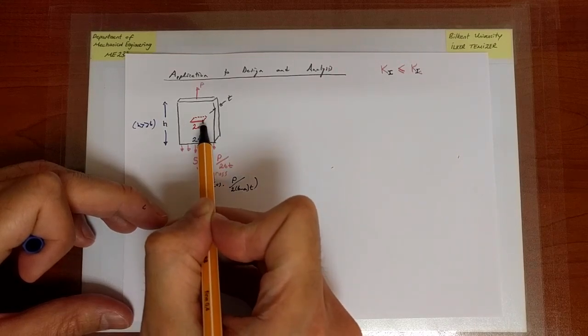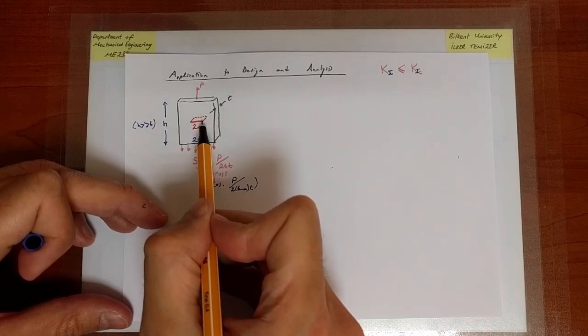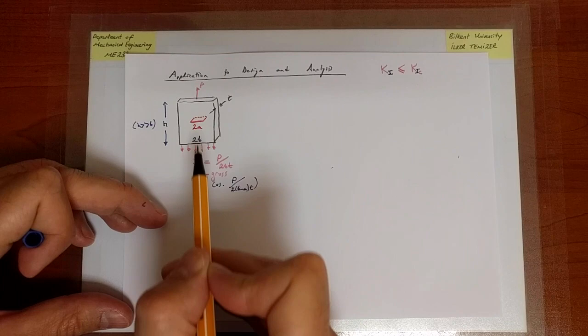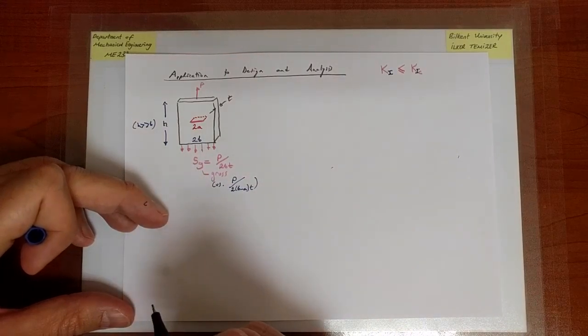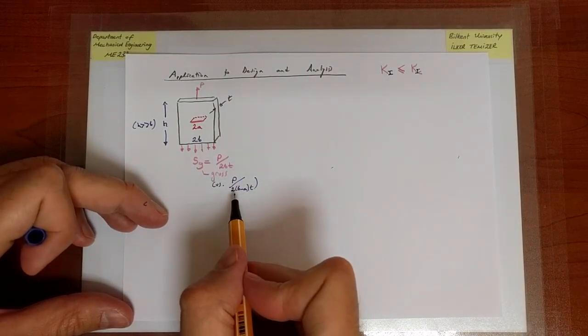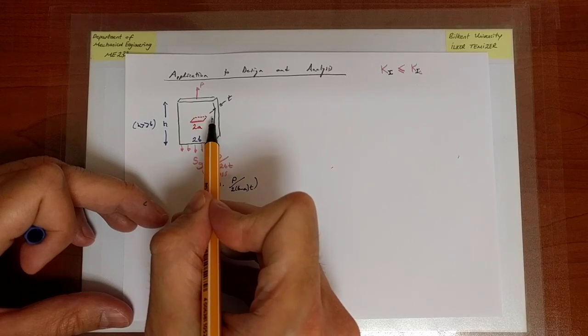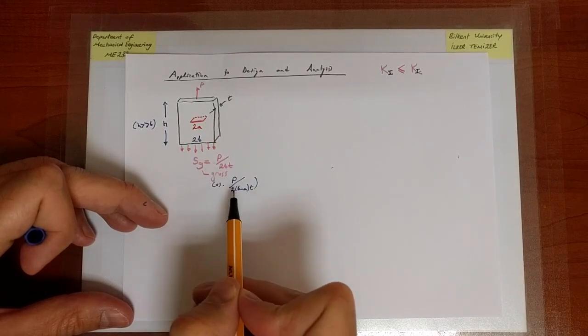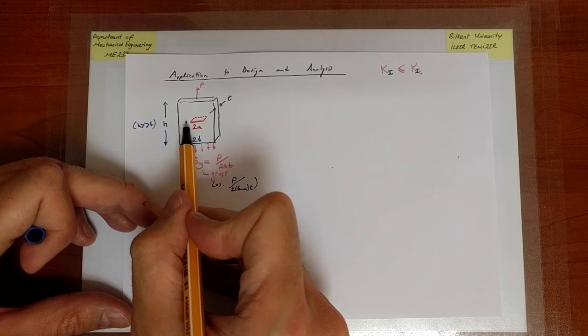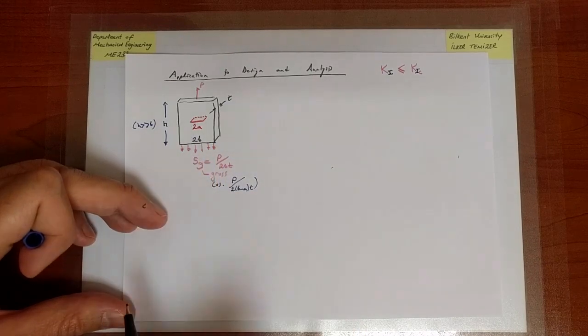In reality, the stress in the vicinity of the crack tip is extremely high, and in fact, according to the elasticity assumption right at the tip, we've seen that it's actually infinitely large due to an infinitely large stress concentration. But it rapidly decays away to the gross stress value. The average stress value must be larger because the cross-section area here is reduced by the presence of the crack.